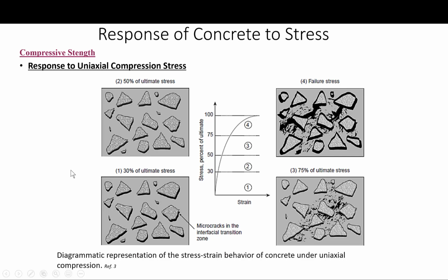So, as we can see here, below 30% of the ultimate load, the interfacial transition zone cracks remain stable. So the stress strain curve here remains linear, as you can see, somewhat. Okay, these are the microcracks in the interfacial zone.